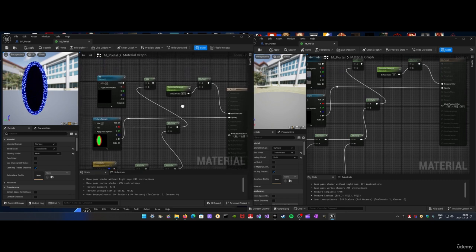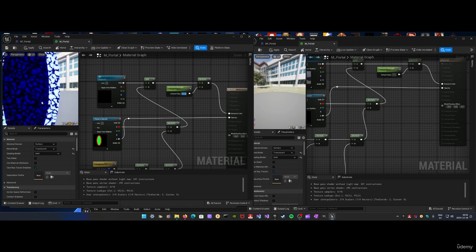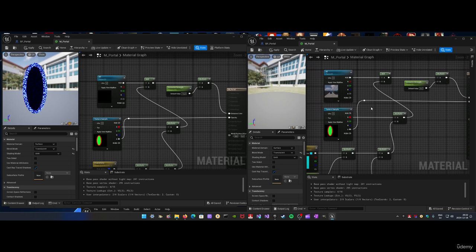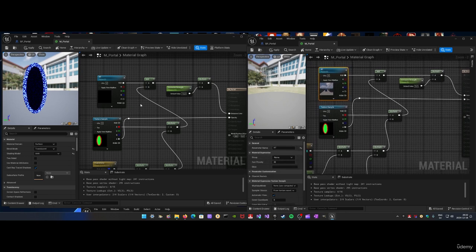And also, let's try changing this emissive strength. I'm not sure how. If we change it to a value of 50 just for testing purposes. Okay, it becomes much more bright. If you wanted to, you can make it very bright, but I think 50 is really too much. I'm gonna keep it at a value of 10 or 5. Apply and save.